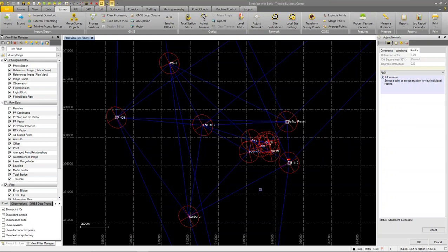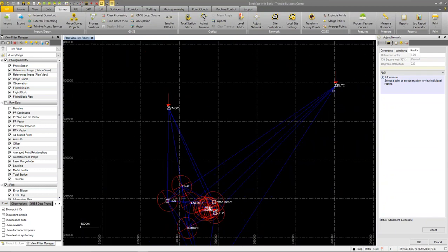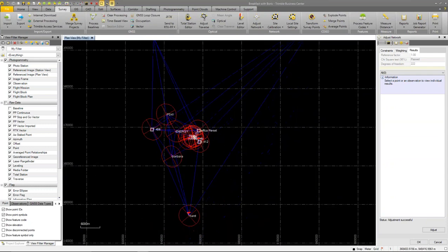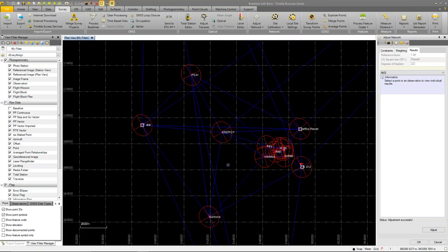Yeah, so really quickly, if you look at the screen right now, what you're seeing are fairly circular-looking area ellipses for my final points. I really constrained geometrically, not perfectly, way out here on one side of my project horizontally, but I'm still seeing rather circular looking error ellipses. That's because GNSS vectors all have the same error source in this project.